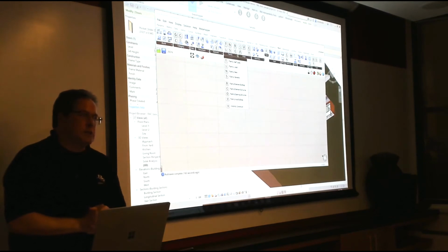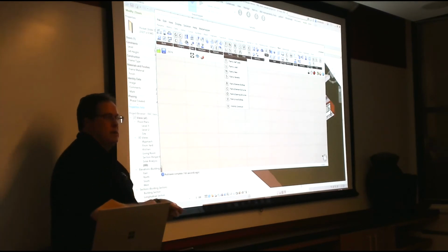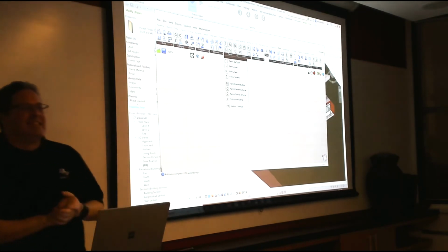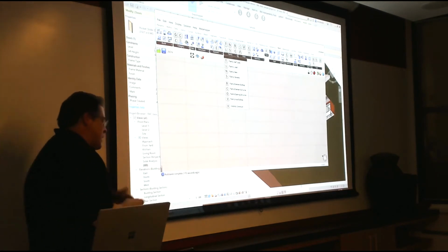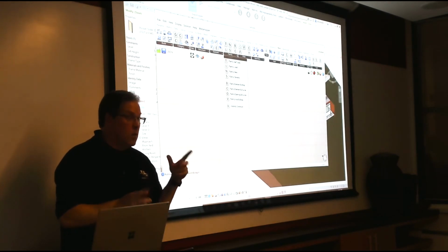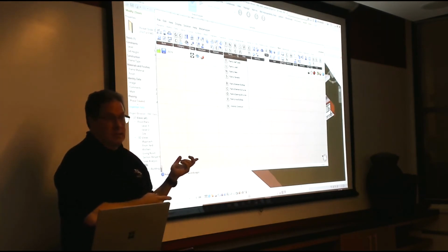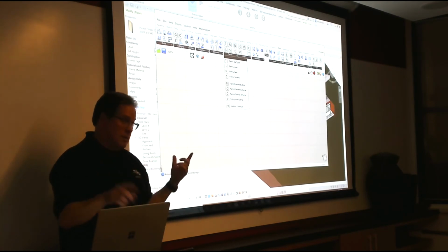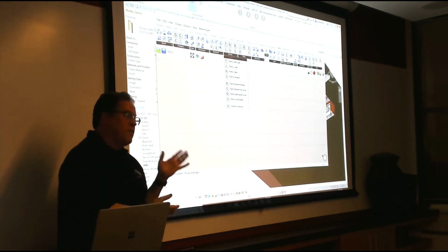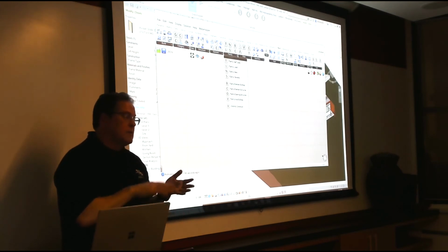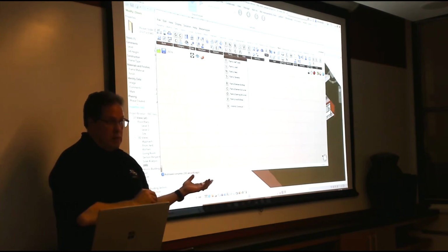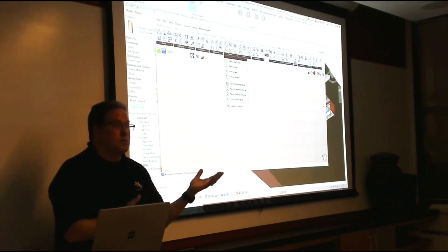Well, and if you have to rationalize, for instance, there was somebody here that had a stair right over here, that was a Rhino stair. All curvy. You could rationalize it by having a series of arcs and straight lines, but I can tell you that stair was not a series of arcs and straight lines. Or you can send a Rhino model and get it machined, and the curve is the curve and it's accurate and it has an infinite number of changing radii. What's really cool about that is I could push that in as a family in Revit and document it to the nth degree. But we still know that the fabrication information is in Rhino. So that's still allowed, that's still part of this process.